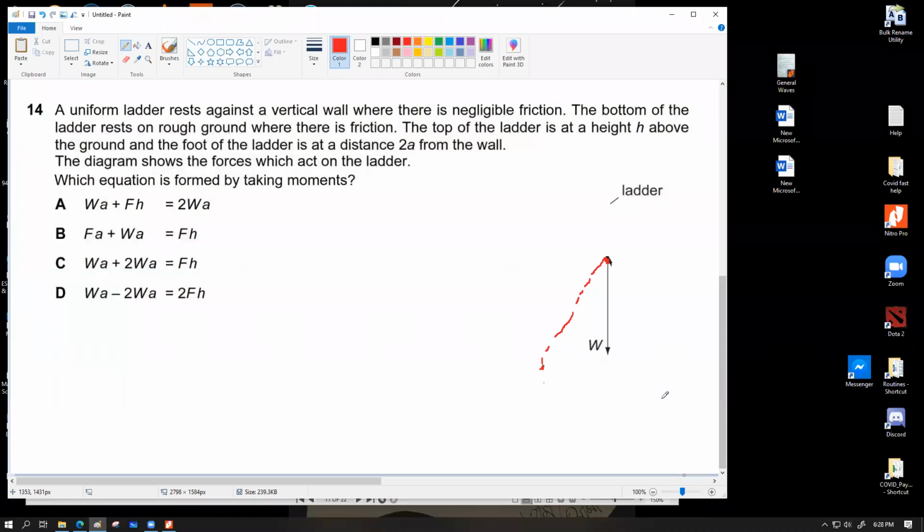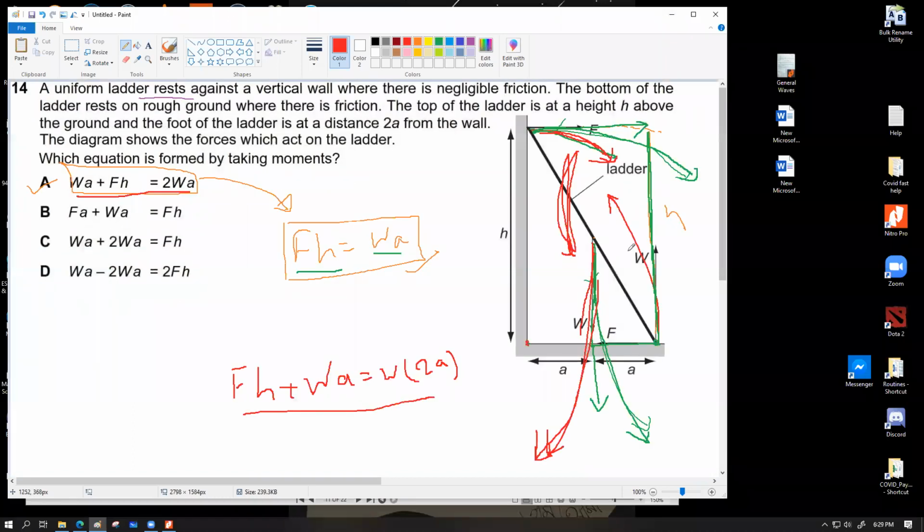So that's another way to easily understand what type of moment you're going to get. Consider one force and one pivot point exclusively. Try to unsee everything around, and that way you can very easily find out what direction of moment you're going to have. So that's why I wrote this as a clockwise moment. Clear?